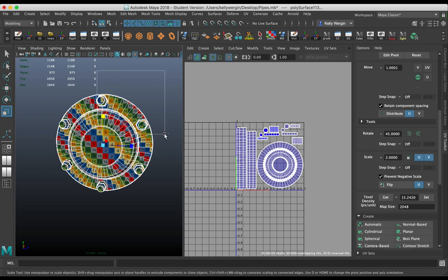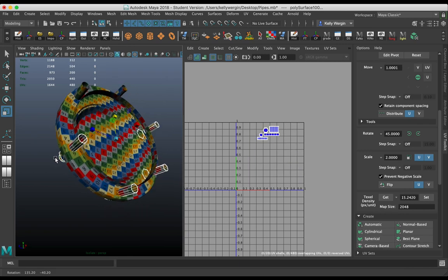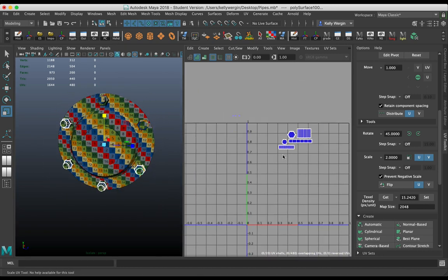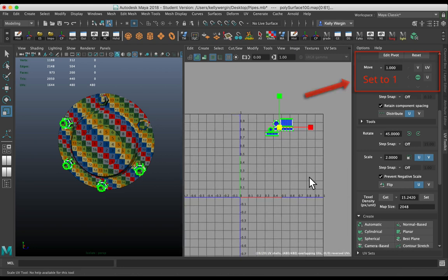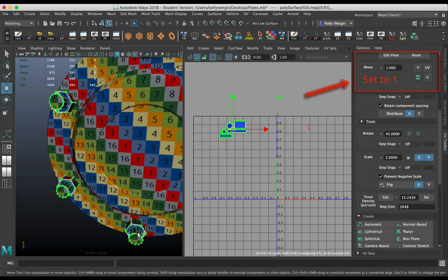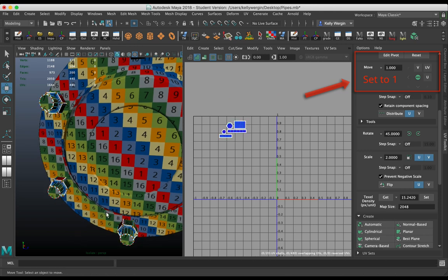I don't want any of that stuff. These are all the duplicates that are sitting over top of these. If you grab the UVs and hit the arrow key on the keyboard, it's going to do something called poly edit UV. And if I hit left, notice that nothing changed on these. It's going to move these all exactly over left 1 quadrant.